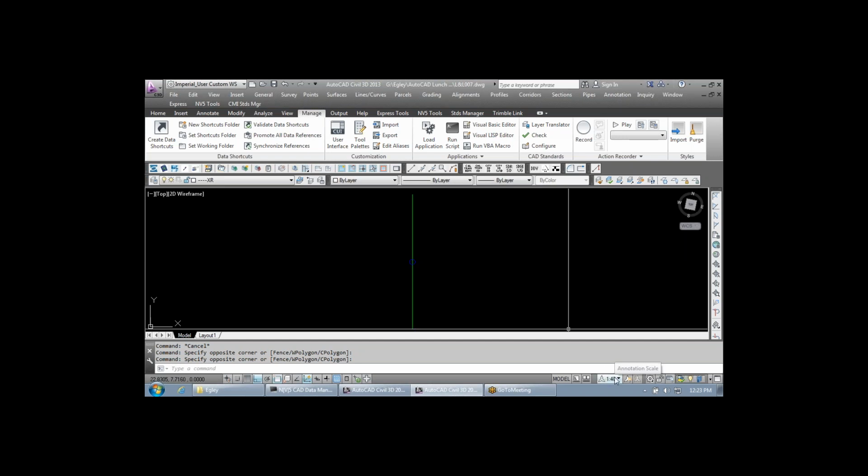So hopefully in this update, which you will get out today, the first thing you'll notice is if you go down to your annotative scales, this list has been reset. You no longer see 20 different scales. There were a bunch of architectural scales. I've actually gone through to the registry and edited it down to just these main civil scales. You can always add to this list. However, this is the list that we're going to start out with. So this will clean up your drawings significantly.